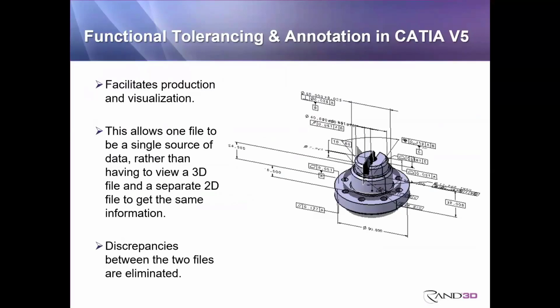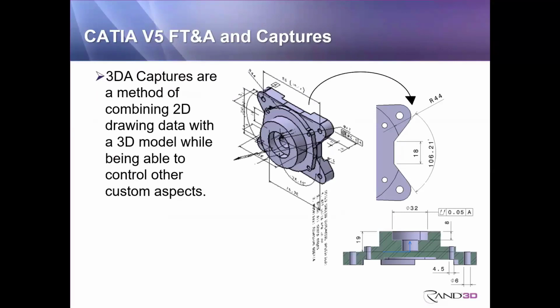So we have this capability inside of CATIA's 3D FT&A workbenches, but the problem is that when you open up a file, and it looks something like what you would see on this slide here, just a bunch of chaos all around, how do we have CATIA help us out by, in the case of maybe a detailed view, going into a certain spot with a camera, or maybe if it's a section cut view, how do we tell CATIA to both zoom into that particular area plus section cut it? So this is where we're going to tie in having the pre-existing FT&A data, but incorporating our captures.